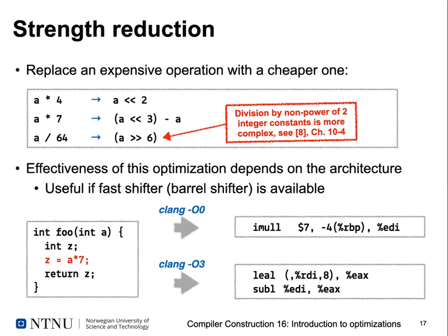For example, if you have one of these very tiny ARM cores for microcontrollers, a Cortex M0 core, you can actually choose between two different multipliers when you design the hardware. Essentially, the multiplier in one configuration may take only one cycle, whereas the multiplier in the smaller configuration is slower and takes 16 cycles to multiply. So replacing a 16-cycle multiplication by a shift would be a useful approach, whereas replacing a one-cycle multiplication by a shift and a subtraction would maybe even result in slower code.